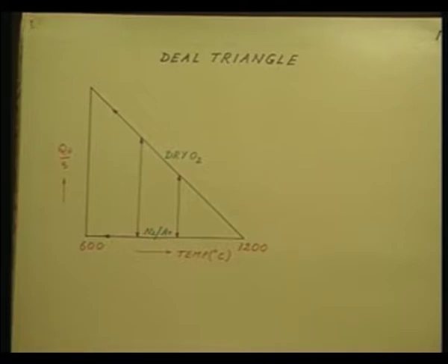What can be done in order to stop this incomplete oxidation process? Well, what is done is this, that at the end of the oxidation process, that is for the stipulated period of time you carry out the oxidation, at the end of this period close the oxygen gas flow and create an inert ambient, that is nitrogen or argon, and now reduce the temperature in this